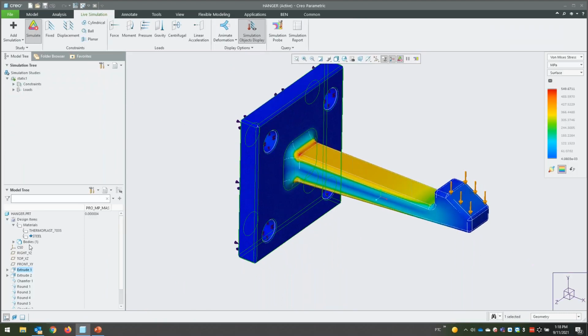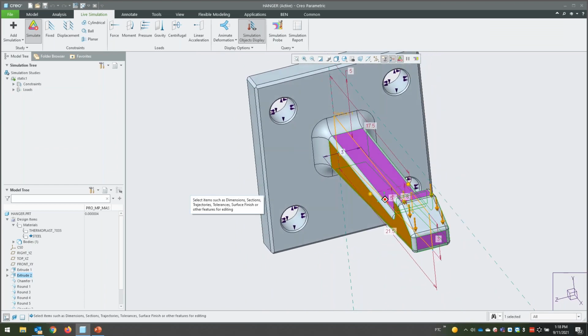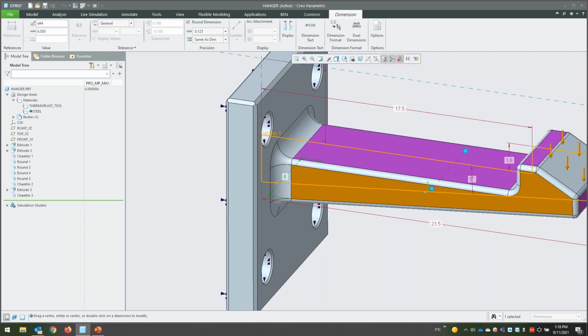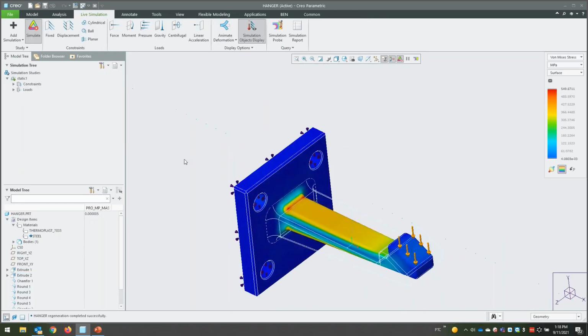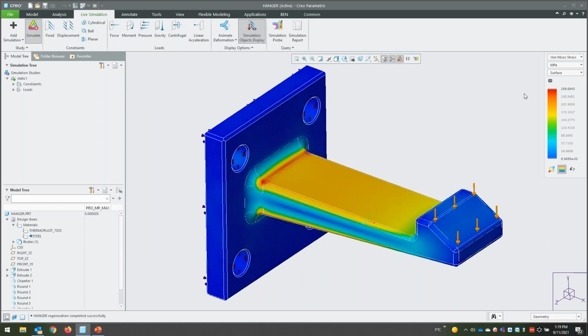So it's not that one. So the width here is 3. If we had 540 megapascals or something before, if we change this to 6, okay, and I just complete that. All right, so it goes away now, but as soon as I'm finished with that, it goes away and starts to remesh, recalculate the results.